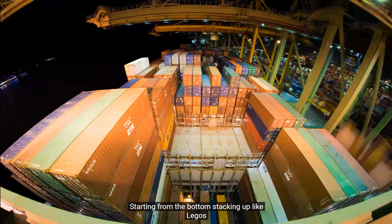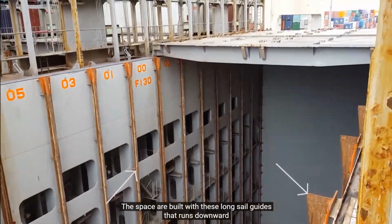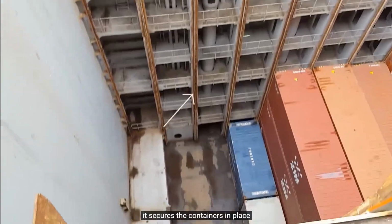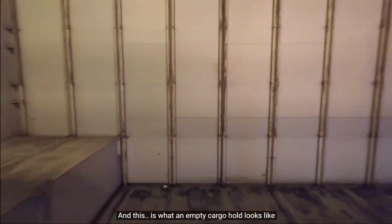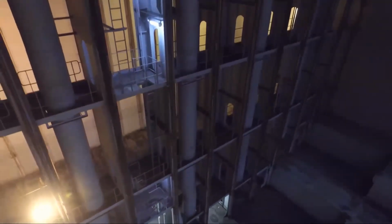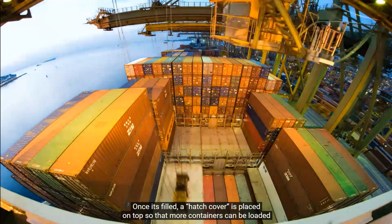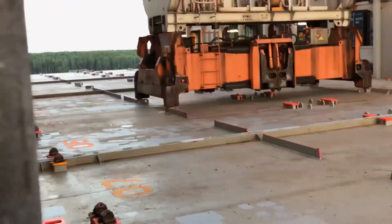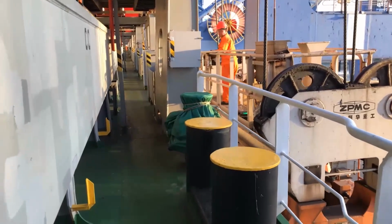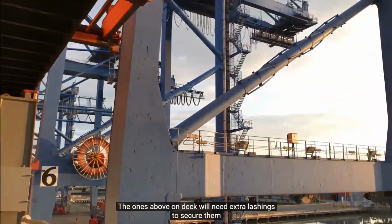Starting from the bottom, stacking up like Legos. These cargo holds can be as deep as 40 meters. The holds are built with long cell guides that run downwards. It secures the containers in place. And this is what an empty container hold looks like. Once it's filled, a hatch cover is placed on top so that more containers can be loaded. The ones above on deck will need extra lashings to secure them.